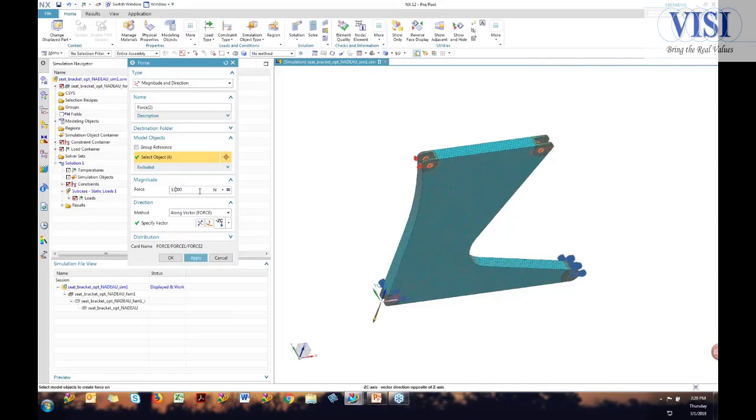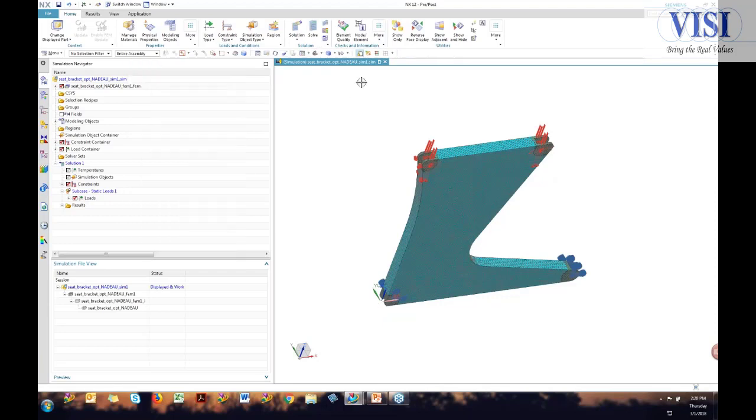Now, for instance, maybe you didn't know the value in newtons, or maybe you wanted to specify it in a different unit system. You could specify whatever you wanted here. This is one nice thing with the units. Maybe if I knew this value in pound force, it's about 2,400 pound force, so I could enter it like that. Those are inconsistent units, but at least I have the same values. That is not a problem inside SimCenter in this type of solution.